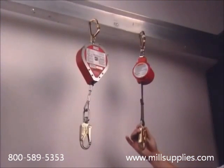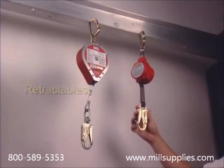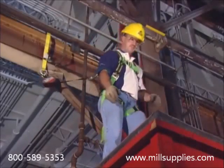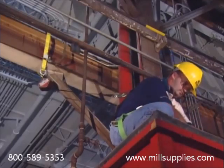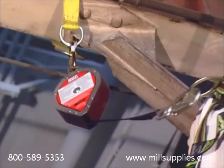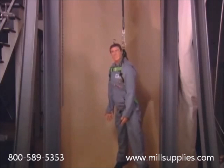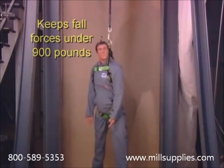The second category of connecting devices is retractables, also known as fall limiters. Retractables consist of a length of webbing or cable wound on a lightly tensioned spring-loaded drum. As the worker moves away from the anchor point, the retractable pays out the webbing or cable. As the worker moves back, the unit retracts the excess material. Should a fall occur, an internal braking system engages and arrests the fall while keeping the forces at about 900 pounds.